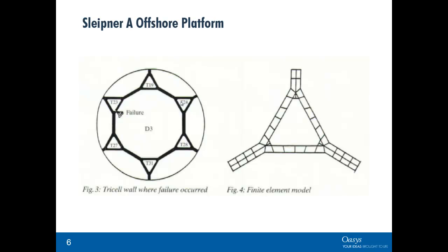Subsequent investigation found that the FE meshing was quite inadequate, and there's a section of the model on the right hand side. The lack of detail in the mesh meant the shear stresses, for example, were underestimated by nearly 50%. So the reinforcement design was well under capacity as well.